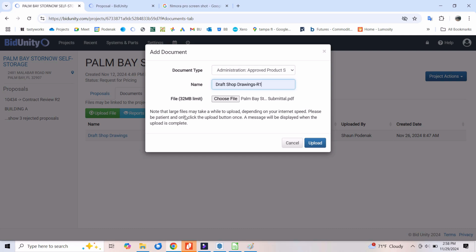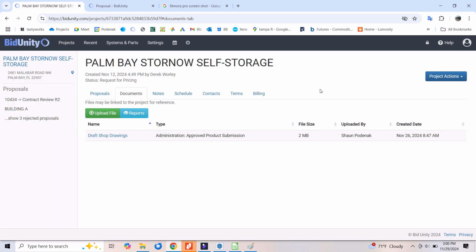And I keep on using the phrase shop drawings and submission drawings interchangeably. We really should try to only refer to our shop drawings as shop drawings when they include the dimensions of the thing that we intend to build exactly. It's created some confusion on some of our other projects. We should refer to the drawings as submission drawings when they're only relating the planned dimensions, not necessarily the intended fabrication dimensions. And of course, the next step is to send it.